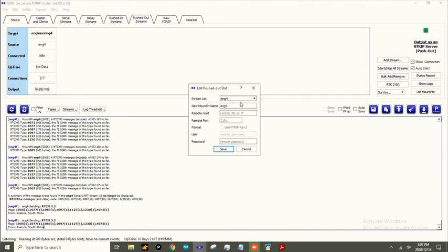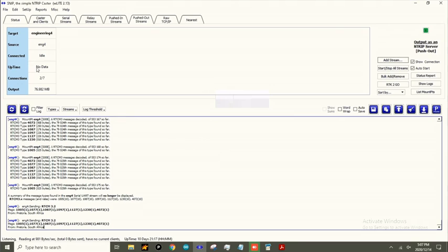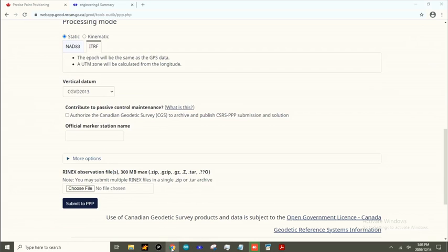Once that is done, we have now successfully set the stream that it's being received. So we're passing that input data stream. It's getting all the RTCM correction messages. We configured those to be pushed to RTK2Go. So prior to us starting this stream to RTK2Go's service, let's just quickly open up the status page for this particular mount point of ours.